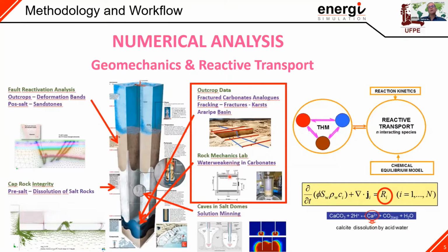And finally, I would like to mention a project that we have with Petrobras, and the person there who is with us is Edgar Poyati. We are studying the possibility, together with my colleagues Leila Brunet and Licia Mouta, and a team of students and a postdoc, Jonathan. We are working on caves in salt domes using solution mining techniques. So the idea is to inject seawater and produce brine and excavate a cave for fluid storage purposes.